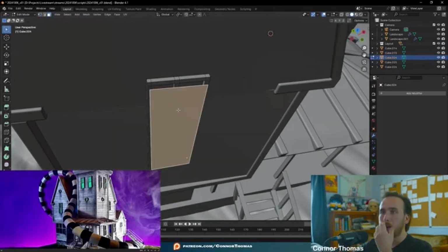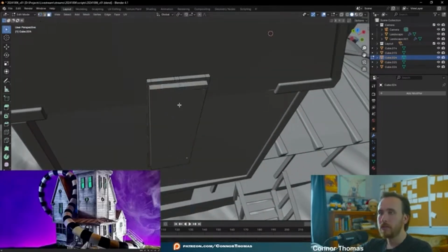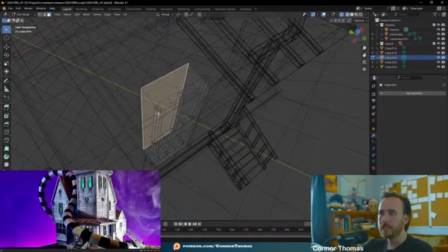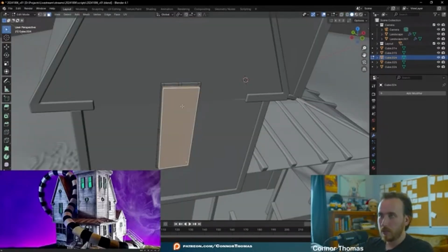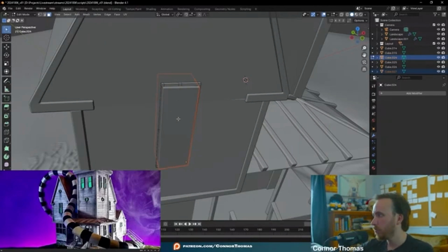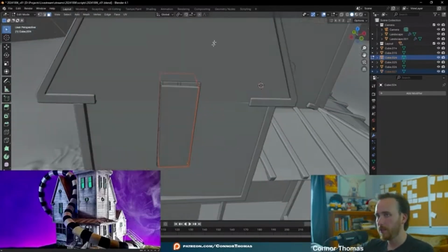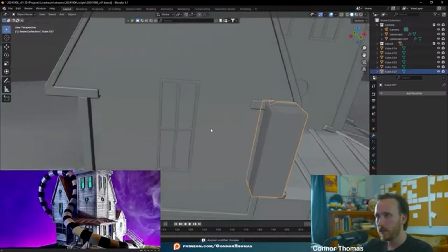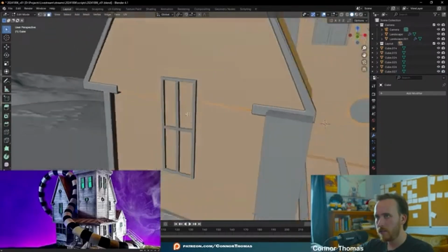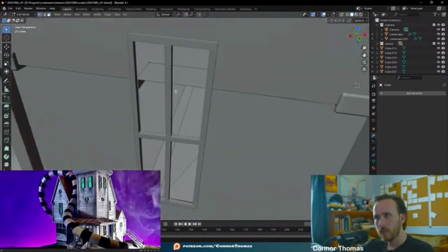But yeah, let's go ahead and grab this guy and then we're going to extrude him inwards. Whatever distance is that you want your window to be in. Let's see. We're going to press Control L here. Make this its own object. Do I need this window again? I need it one more time. So let's select this guy. Boolean, Boolean, booyah. Select the cube. Apply it. Just move that out of the way. And now should work pretty good.